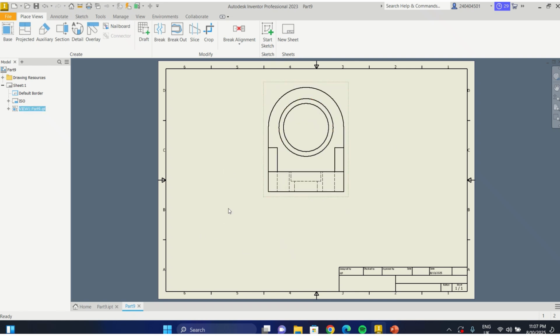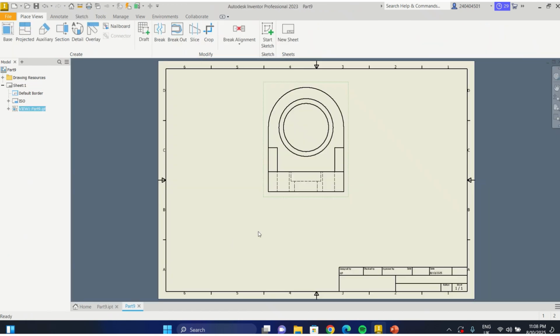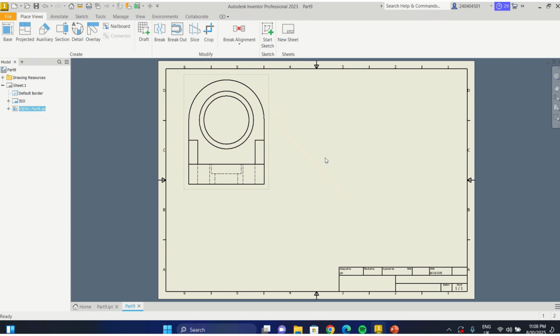Now, what we have here, this area, is what we call your drawing sheet, just like you have on your paper drawing. Okay, I'm going to look at how to place my side view. Generally, this place now will be our side view. And based on first angle projection, you look at your side view from the left and you place it on your right. That means on the drawing, my side view will be on my right hand side here. So let me position this this way.